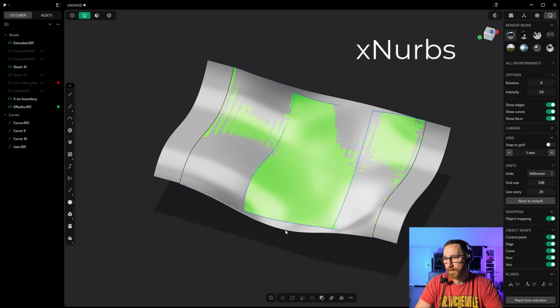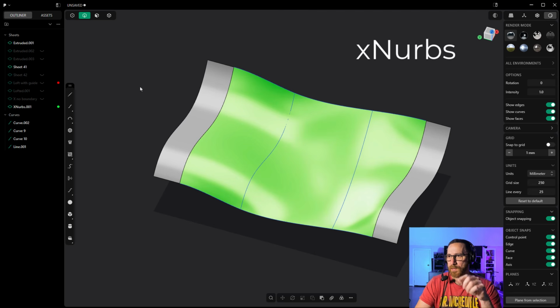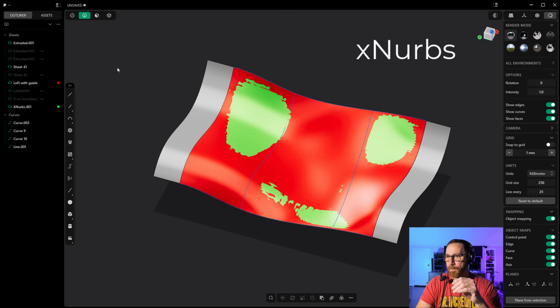And you would expect to see this because the outside varied quite a bit, but you can see that we've got the gray one, which is the version without the boundary. You can see that it's kind of higher here, except for right in the middle. And then the version with the boundary is higher in the middle and then kind of splits the difference on the other side. Now, let's hide this one. This is the version that we made with all of the guides, right? So we had the same exact input for the loft: G1 continuity, complete boundary, follow these profiles, hit these curves in the middle.